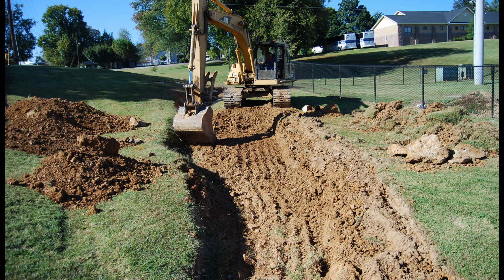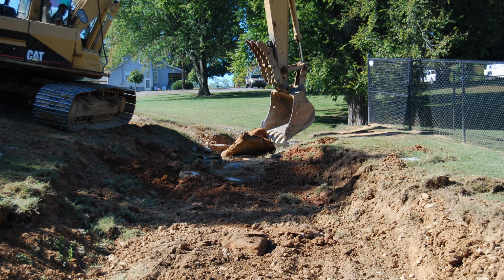We did not dig a narrow channel for the stream with a bed and banks. Instead, we made a wide floodplain that was also the stream channel, and this was done to reduce shear stresses and the possibility of erosion. Large rocks were picked up and saved to place on the finished floodplain.